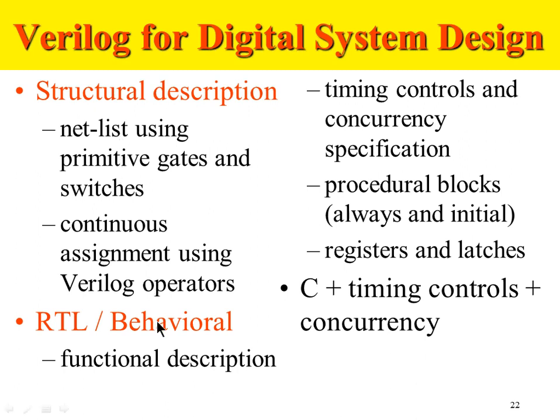Whereas behavioral design, or behavioral modeling, in Verilog is done by functional description. We describe the function of the circuit in Verilog syntax. Then it has timing controls and concurrency specification. So there is a way to develop concurrent logic in Verilog. We do that in behavioral modeling, and we can develop timing controls for clock and other things.